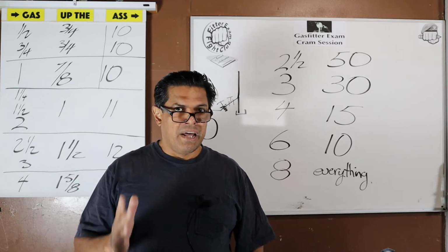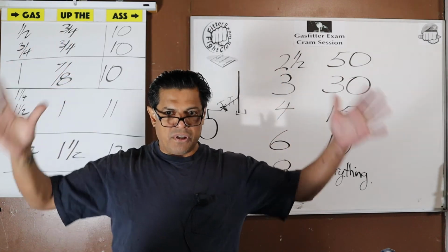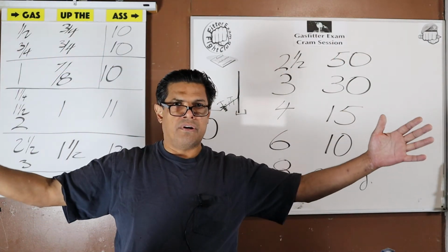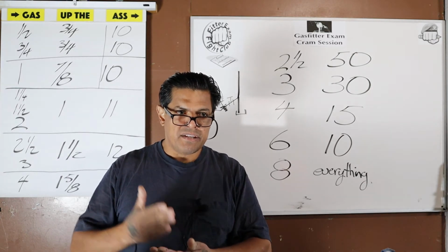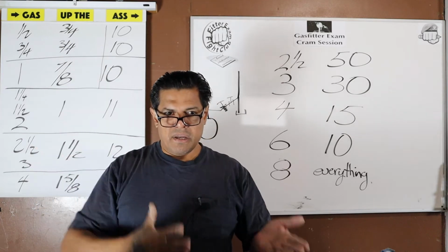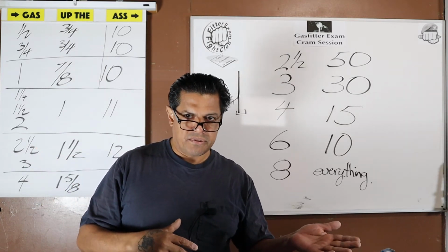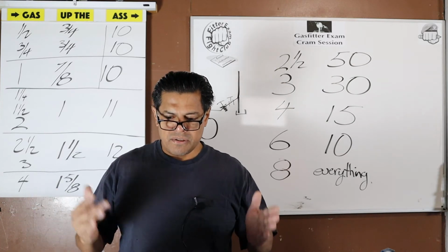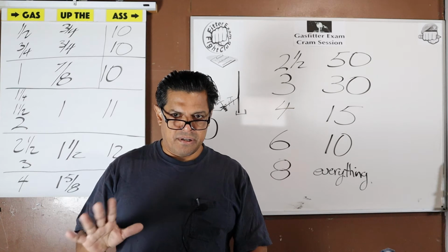Okay? And a plenum can take the shape of ductwork, actual large sections of ductwork. But plenums can also simply be the space in between a drop ceiling and the structural ceiling. We have a return air plenum, but there's also a supply air plenum. There's also an exhaust air plenum. So, plenum by itself is not a no-no.